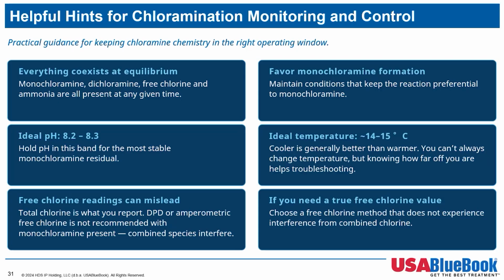And third, this is one that catches people. Don't trust a DPD free chlorine reading when monochloramine is present. The combined chlorine species interferes. Total chlorine is what you report. If you genuinely need free chlorine, use a method that doesn't suffer that interference, such as indophenol.